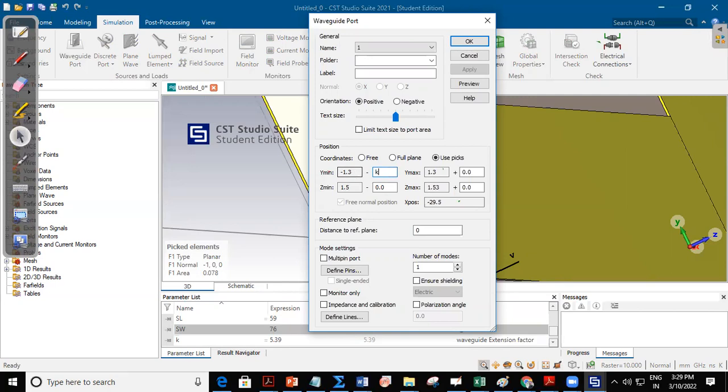We have already defined it. So I'm writing K star SH. SH is also defined already. So K star SH. Copy this for Y minimum, and for Y maximum to 1.3 to this. So it will take from 1.3 afterwards upside. Here also copy it, the same K times SH, and here you write SH only.